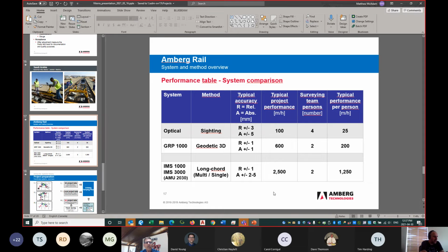Federally, I don't believe there are. And typically we're talking tolerances of about 3/8 of an inch, so like 8 or 9 millimeters. So they're not super tight on those ballasted tracks. Like the statistical data that I was looking at, somebody will come out and measure this geometry if there's a derailment. And then they'll say, all right, well, you're out. So it's a geometry issue.